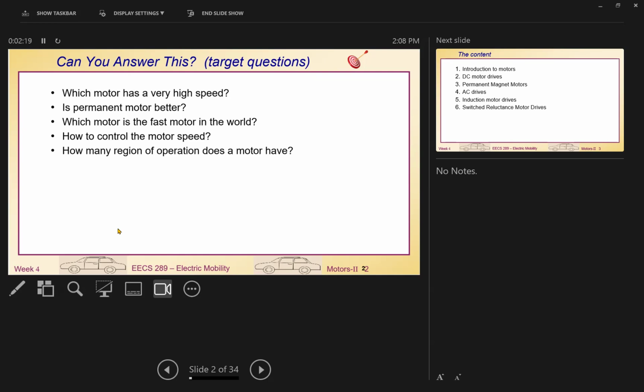So between the rotor and stator, this is called the air gap. The magnetic field will go through here. So in theory, if the air gap is smaller, then we get stronger magnetic power for our motor. That's why many motors are designed with a small air gap, usually about 0.5 to 1 millimeters. That's quite a good standard.